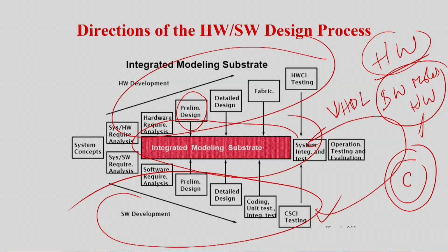The idea is that I have written a Verilog code for an adder. The code will simulate and tell you how the hardware will behave. But if there is a C program which will access this adder, the Verilog simulator cannot simulate that, because the Verilog simulator simulates the hardware which is written in Verilog or VHDL. How a C program running on top of that would be executed on that hardware is very difficult; such simulators are very difficult to develop. Even if one is developed, it is very slow, as it takes the hardware represented in Verilog or HDL, a hardware description language.